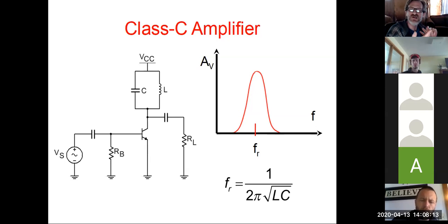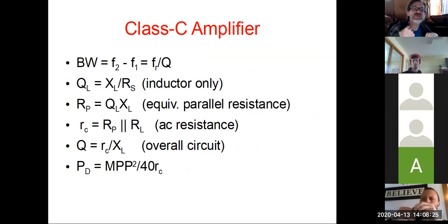So we just have some adjustments to make for the values of L and C to lock in for that frequency, and then establishing what we want for our base and our load resistors. Otherwise, it's a pretty simple circuit. So when we do the design of it, we decide what we want our overall frequency to be. So this is going to be our resonant frequency, 1 kilohertz, 10 kilohertz, whatever we've set it up for. And then we go through and do some design parameters.